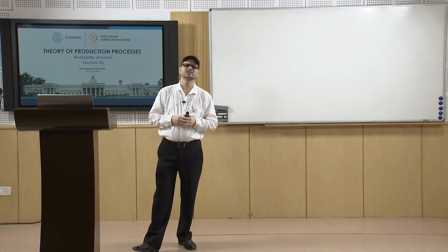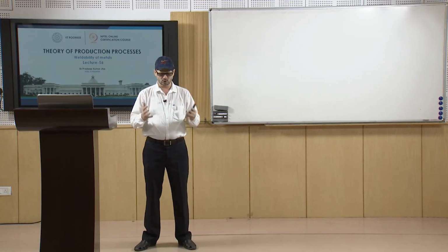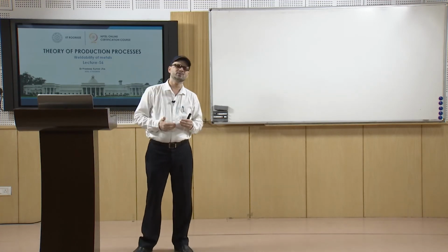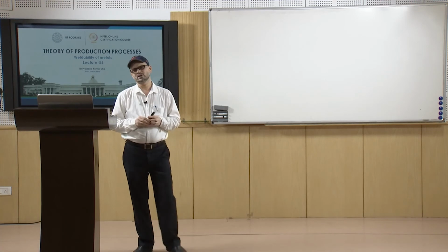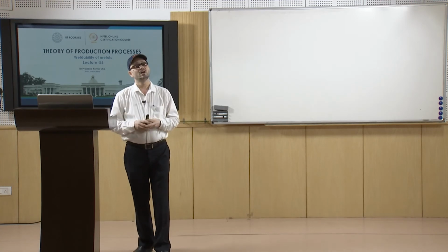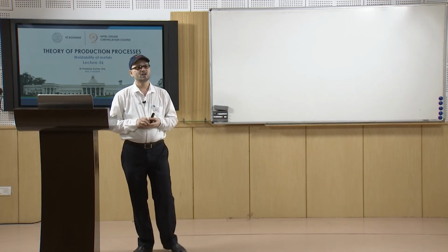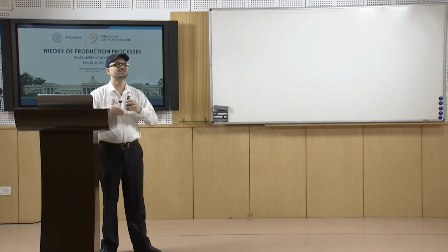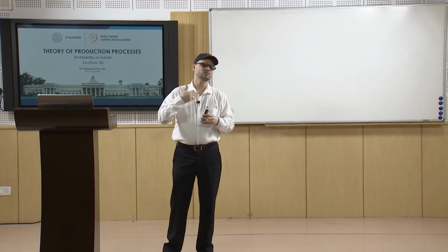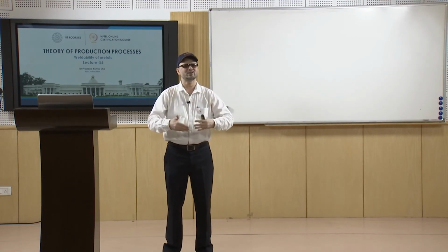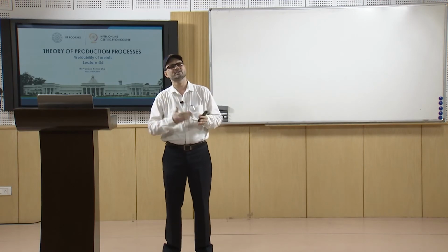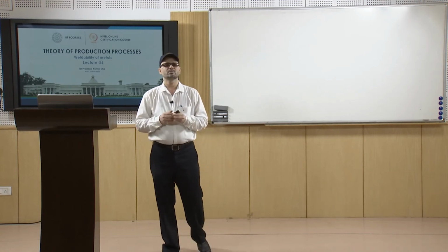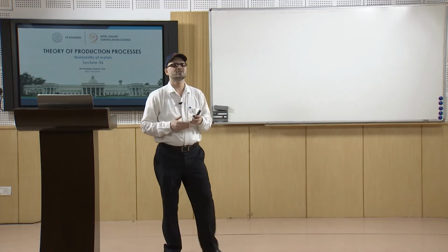The purpose is that by this means we are trying to see that the zone where the welding is carried out, the weld metal zone, has a minimum of impurities and a minimum of phases which are undesirable for the good weldability of the material. So, that is why the effect of these alloying elements on weldability is required to be known: in what way they are affecting the hardenability, in what way they make precipitates, whether they are contributing towards grain refinement, or whether they are contributing towards the ductile to brittle transformation temperature.